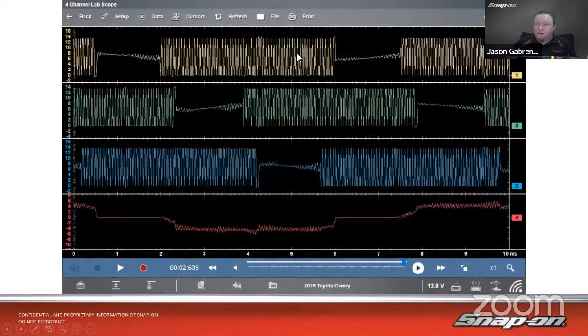All right, so here's my U, my V, my W. They're 120 degrees offset from each other, which gives me a 360 degree turn in there. So I can actually measure how fast it's turning. I can see whether the polarity is up or down by also adding this other channel over here for my current. I could do one voltage with the current at the same time and see what's going on there, just to understand how the voltage and the current flow through that.